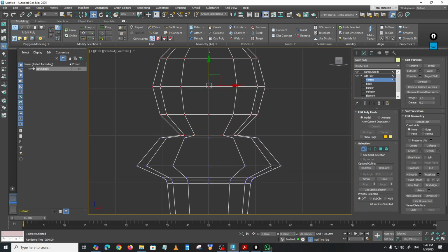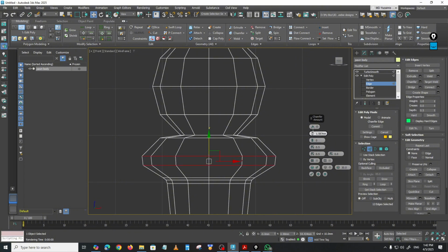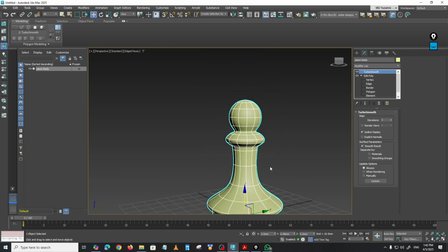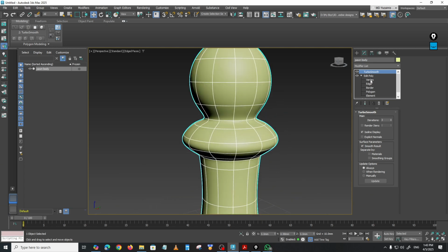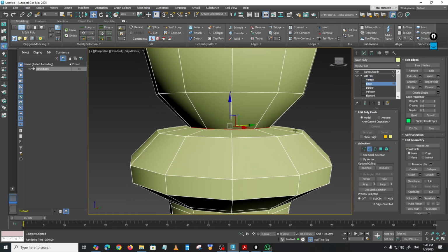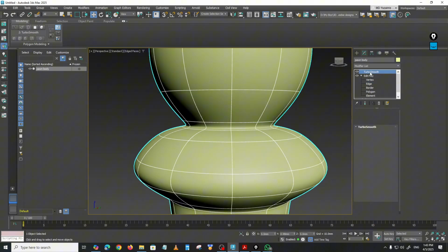Like this. I think I want to adjust this shape a little bit, and maybe chamfer this. Put 0, expand this a little bit, and hit OK. There you go. Alright, nearly there. This is not sharp enough, so I'm going to go to the vertex or the edge, double click on this edge loop, and then hit the chamfer again, just lower the value a bit, hit OK, and that should sharpen the corner.